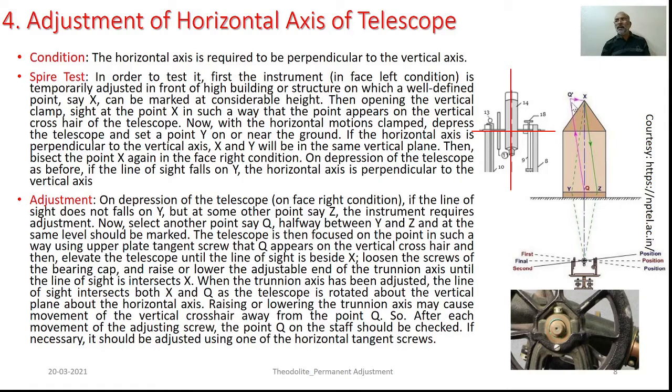Let's bisect a well elevated position, say 40 to 45 degrees above the horizontal plane, as X, with both the motions clamped in the horizontal plane. Let's have the telescope moved in the vertical plane.